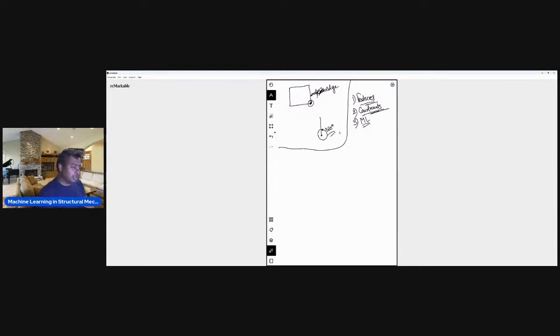So every element has its own set of features, namely the vertex, edge, face, whatever. And then on top of that, you impose different types of constraints which make the merger possible. Instead of doing it in a traditional sense, you can do it in a machine learning sense. And then, like you get a map from your local node numbers to global node numbers, you will directly get a k local to k global map.